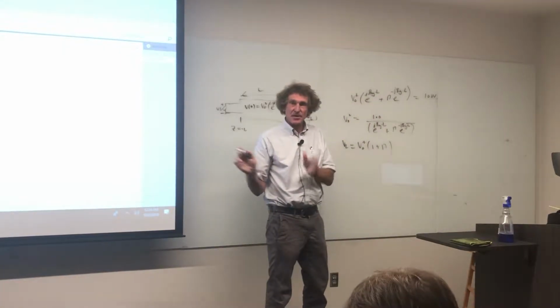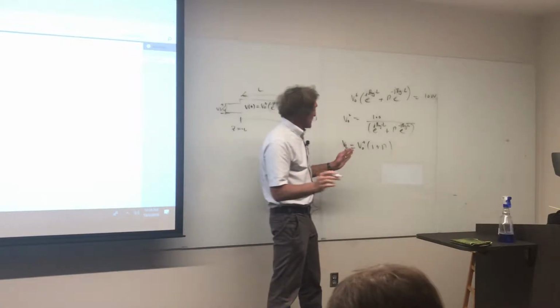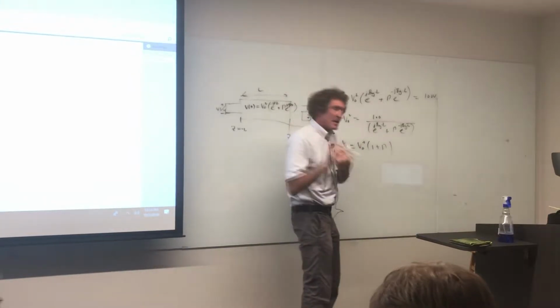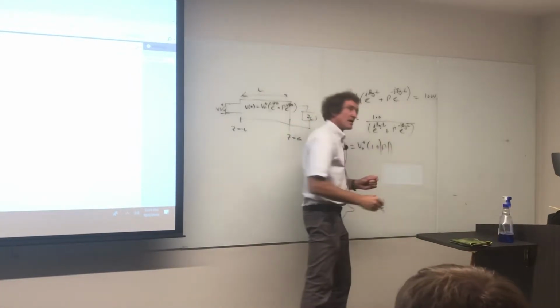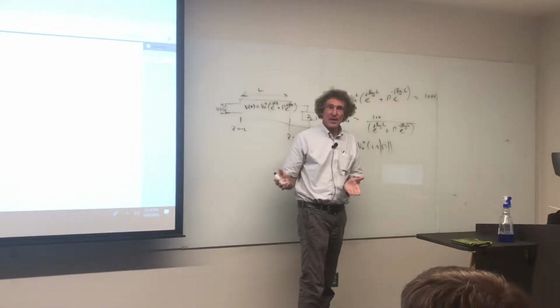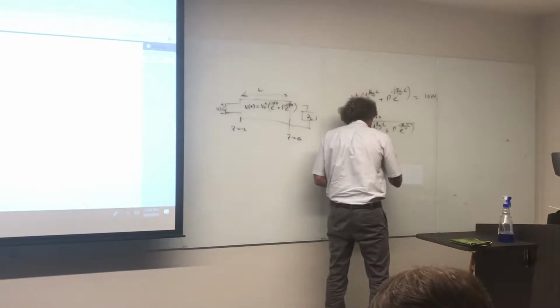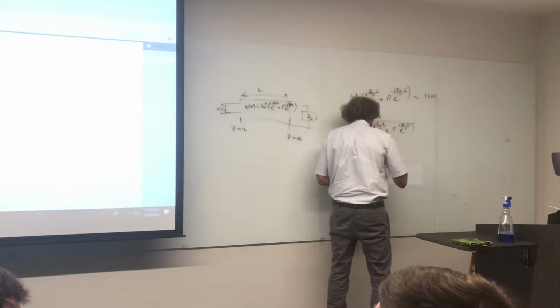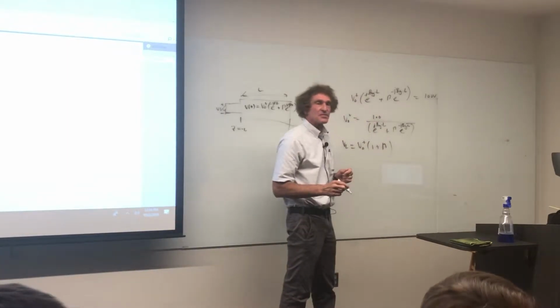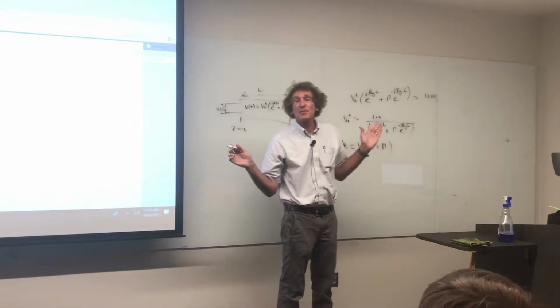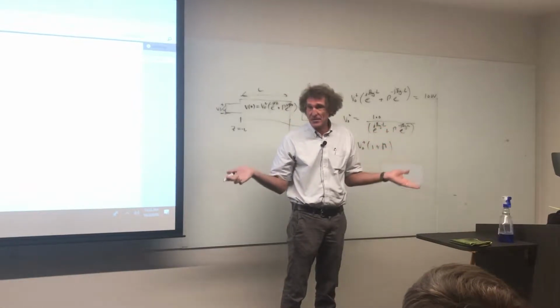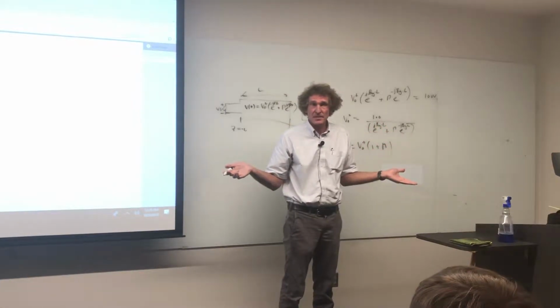Here's something else I saw, and I don't understand how. People get V0 plus right, and then they do this. That's wrong. All right? It's not the magnitude. It's 1 plus the actual reflection coefficient here times V0 plus is V load. And I just cared about the magnitude. If you gave me just the magnitude of VL, that's all I wanted. I didn't want the phase.